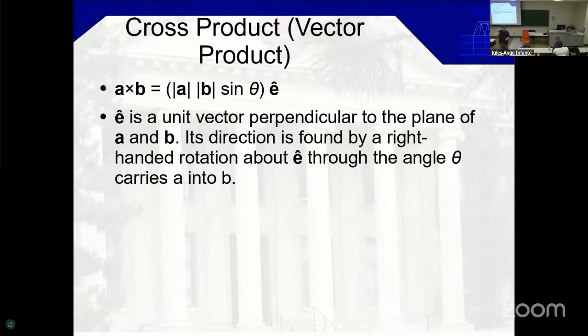So you can measure the station between those stakes, and then you can measure an offset. An offset is perpendicular. So you have those stakes, and perpendicular to that, either right or left. If this is increasing in station, we always look from the lower station towards the higher station. And now this becomes offset to the right and offset to the left. And so we measure this offset.